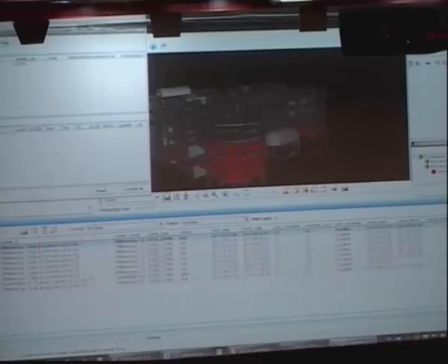And then I'm going to go to the objects and pay attention that this activity is actually on floor 3, I think. Yes, it's on floor 3. So in the object properties, I'm going to go ahead and I'm going to make my filter. And by the way, if it wasn't for the naming convention that BIM are following religiously in the member mark, they would make our job almost impossible.